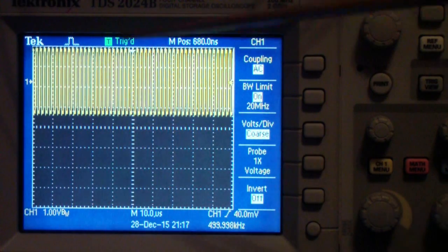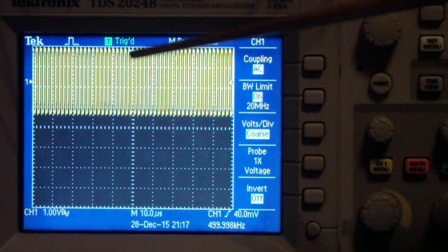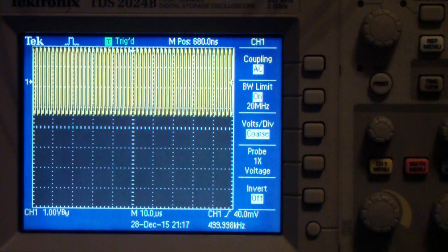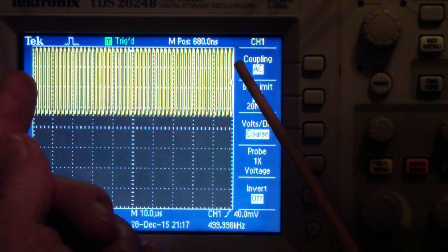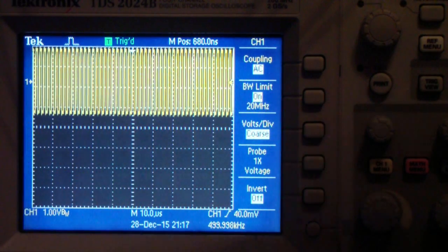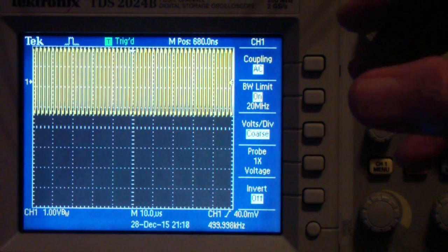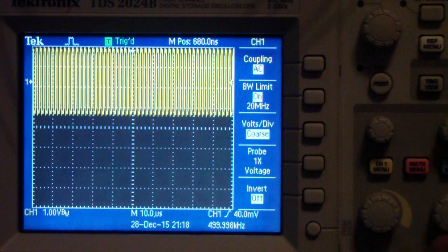It's more a question, when you're doing an FFT, of how many cycles of the waveform you have displayed, because the FFT is simply going to use this amount of information, and it is translating cycles into the frequency domain.